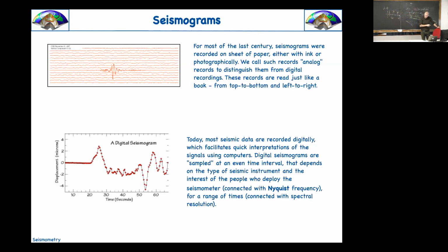And what does that mean? That you can say, okay, we don't care. We make a filtering and we can use this one. Good. But if delta t is too large, 1 over delta t is becoming too small. And maybe they overlap. And we have the aliasing problem. That's why when you hear about anti-alias filters, they are trying to avoid that.